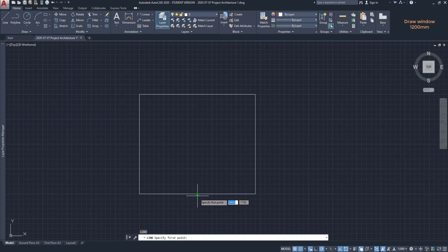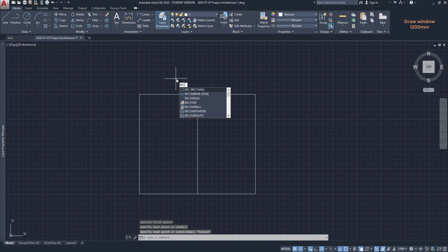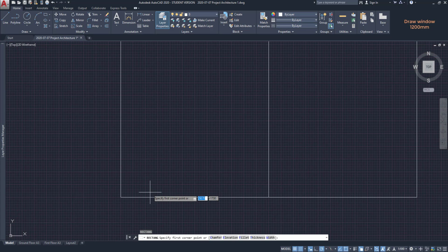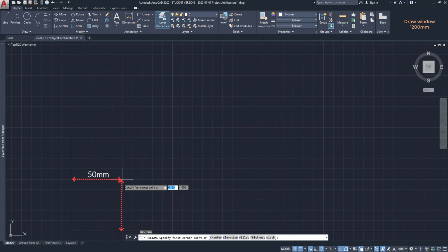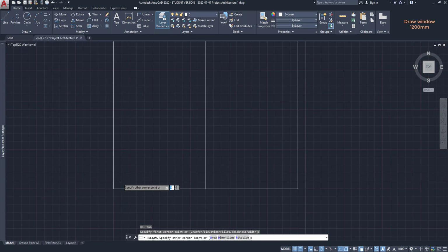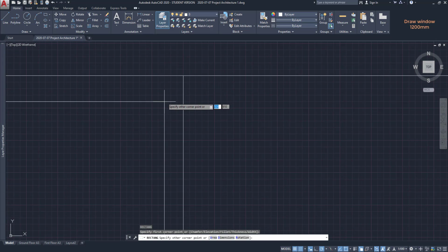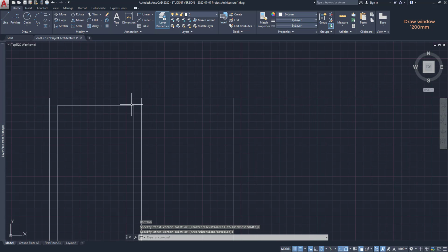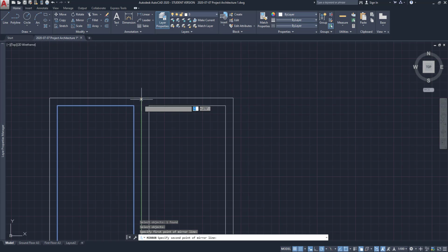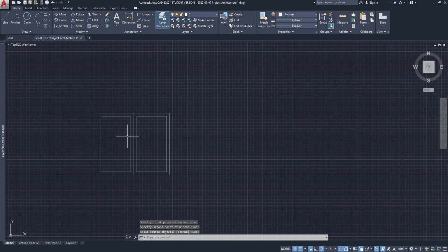After, I draw a line from the middle point until the top. And then I draw another rectangle, and this is how you understand how the grid is useful. I click in this point, as I know that 5 small squares measure 50 mm. Then on the other side, I click in a point with the same distances to the corner regarding both axes. Then I'm going to use the command mirror, and using this midpoint, I copy the rectangle to the other side.